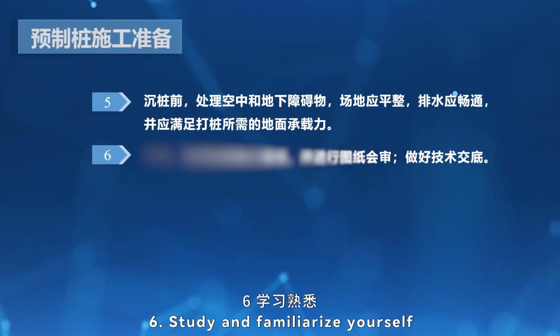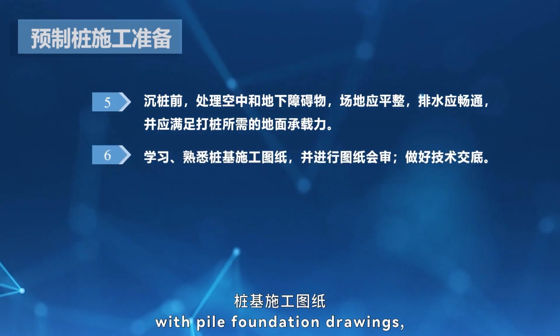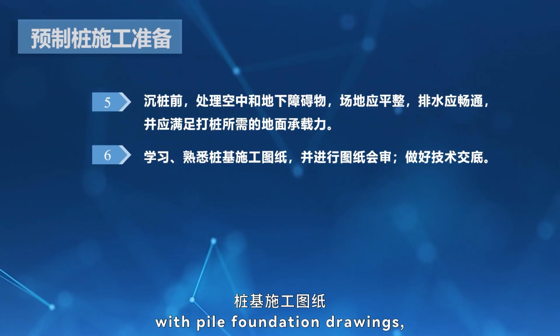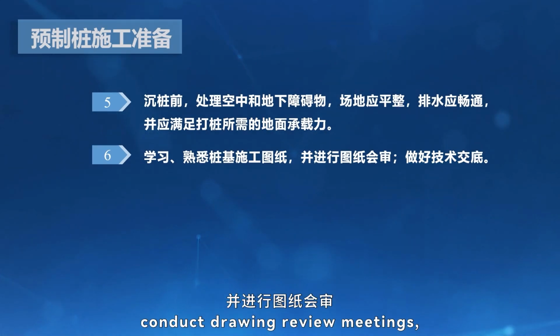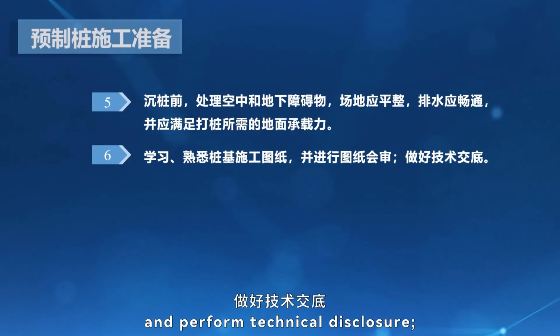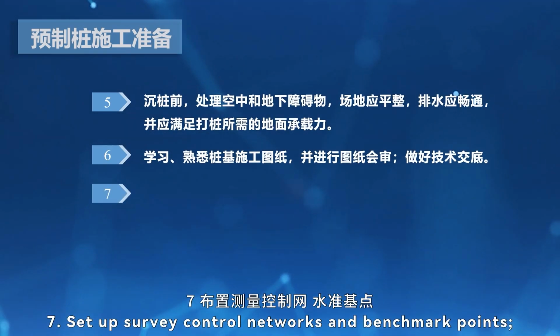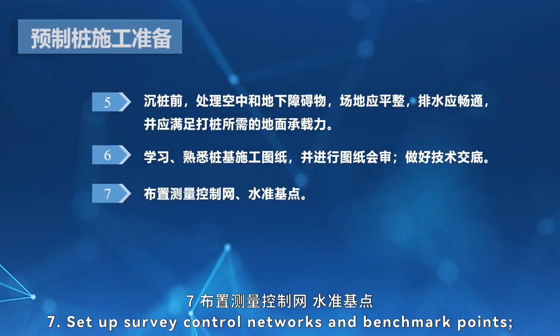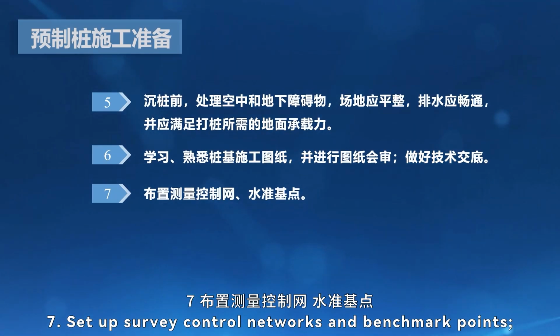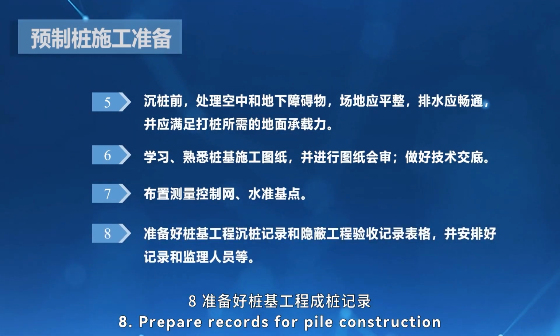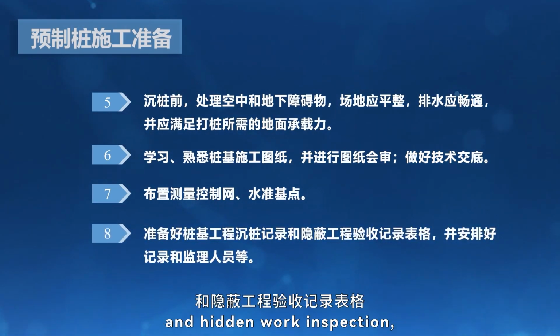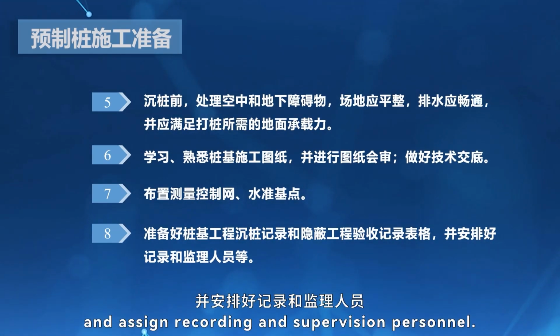6. Study and familiarize yourself with pile foundation drawings. Conduct drawing review meetings and perform technical disclosure. 7. Set up survey control networks and benchmark points. 8. Prepare records for pile construction and hidden work inspection, and assign recording and supervision personnel.